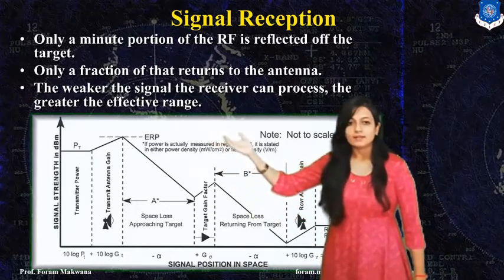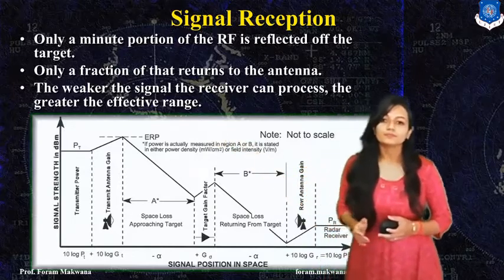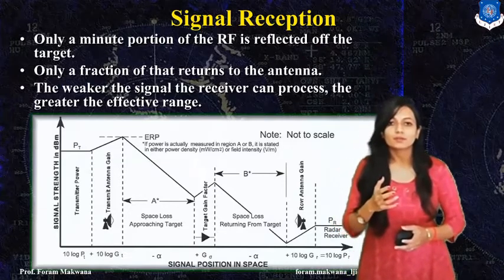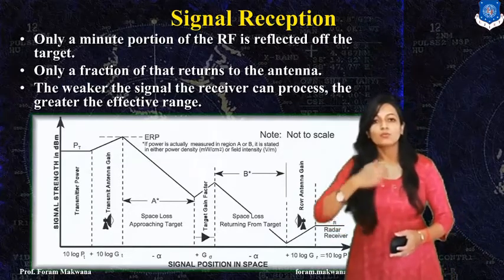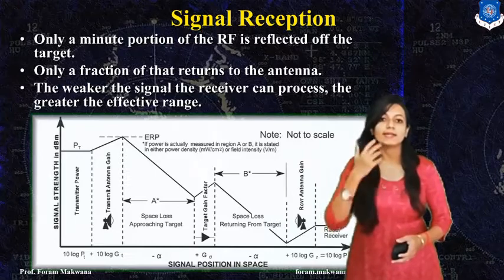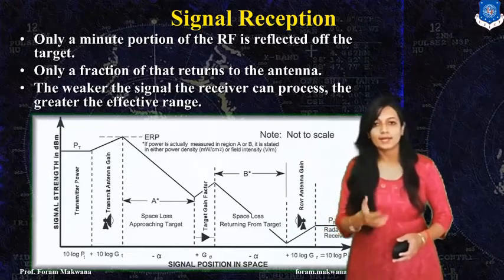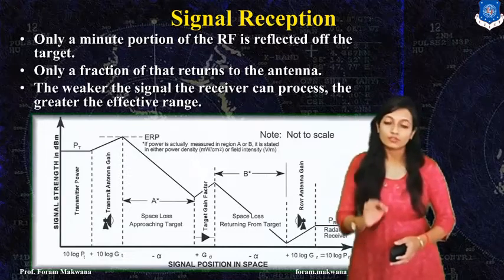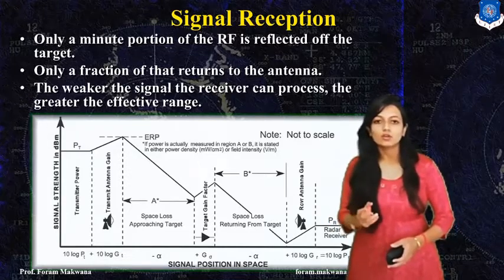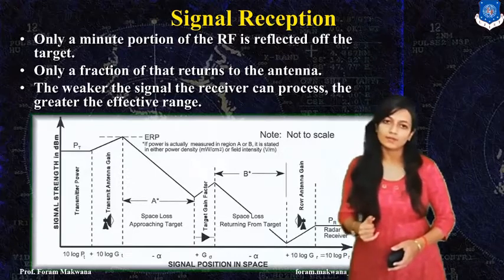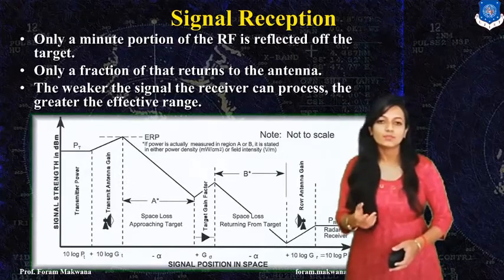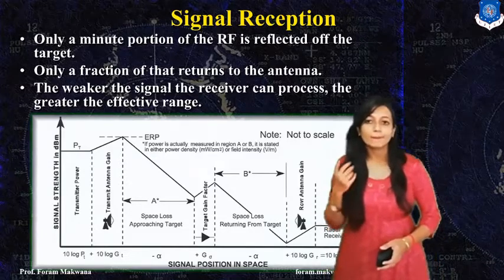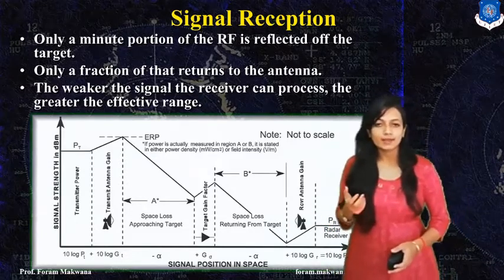transmitter antenna gain. The antenna gain is a must because how much power is going to be transmitted directly depends on the gain of my antenna. And we know that the multiplication of transmitted power with the gain is called the effective isotropic radiated power, that we have already studied in the subject satellite communication. Right? It is a product of PT and G.